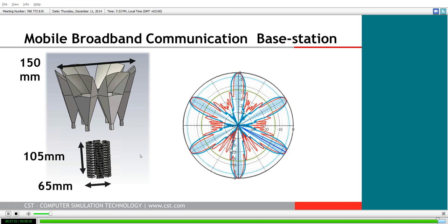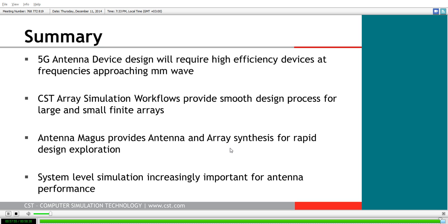More importantly, though, when we actually look at the resulting form factor, our arrangement of horn antenna arrays is providing us with the required gain and coverage with a much smaller form factor, particularly in terms of the width, compared to the sectoral horn antennas. So this likely makes it a much more attractive candidate for subsequent in-detail study for the design.